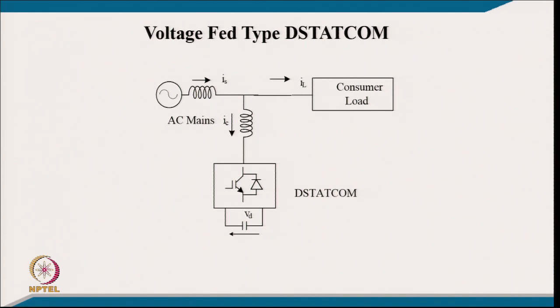That is the reason this voltage fed or voltage source converter D-STATCOM has taken the lead, and commercially these are in practice. Of course, as far as research is concerned, the other can also do the job, but out of the two options you consider the best option for you. So, the voltage source converter fed D-STATCOM is considered better than the previous one, and it is used in practice. That is about the converter based classification.